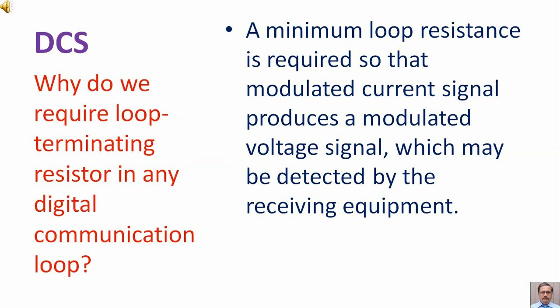Why do we require loop terminating resistor in any digital communication loop? A minimum loop resistance is required so that modulated current signal produces a modulated voltage signal which may be detected by the receiving equipment.